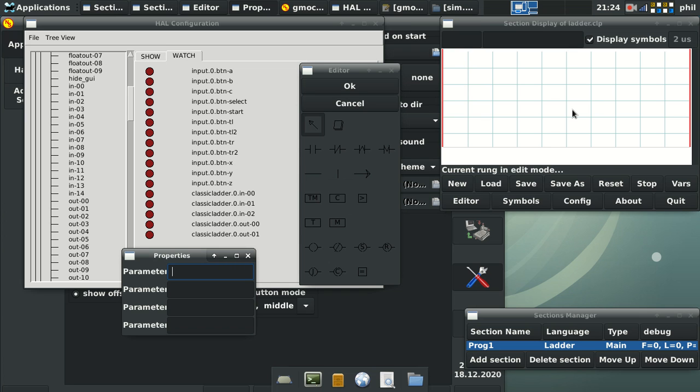Looking at PLC, PLC is read from top to bottom, left to right. So from left to right, I have inputs, I have processing that goes on within the PLC, and then I have outputs. So think about lube pumps, coolant pumps, door interlocks, things like that.